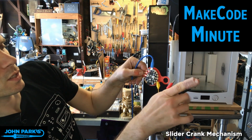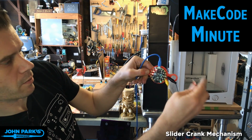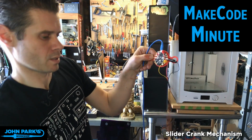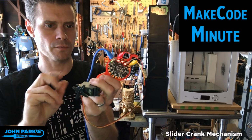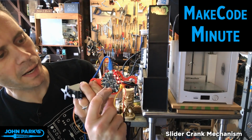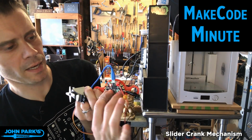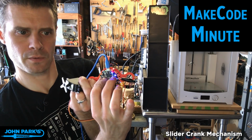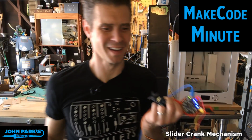There. You should normally power things off when you're plugging them in, but we'll live dangerously. This black one is going to go to ground, and this is power. And so now you can see we're going back and forth between those two minimum and maximum angles. If I switch to this other mode, I can now use the buttons to go back and forth. Okay. So that was the MakeCode demo, not quite a minute.